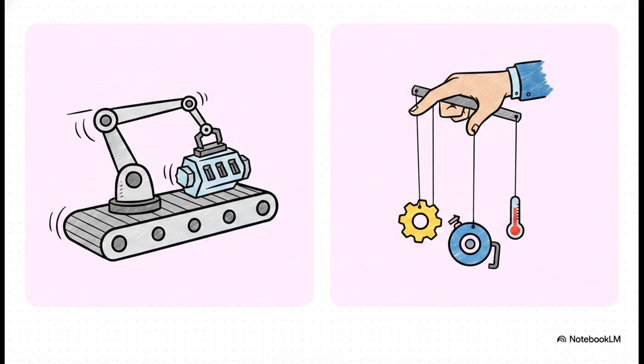So the really crucial takeaway here is how these switches totally alter the engine's behavior. In its automated default state, the engine is calling the shots. It waits for a full start sequence, it runs its own automated prelube, and it manages its own idle timing. But the second you flip one of these override switches, the technician takes the reins. You want a direct starter test without actually firing the engine? You got it. Need to force a manual oil prime to check your pressure? Done. It's all about handing complete, granular command over the machine subsystems right back to the human.